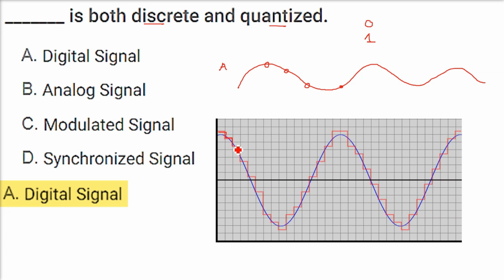Now what you do is you take a sample and then you quantize it to 0 and 1, right? Sampling and quantization of the analog signal is done. For example, you get some 0.5 value or 0.6 value. 0.6 can correspond to 1 and 0.4 can correspond to 0. And these are nothing but the voltage levels.